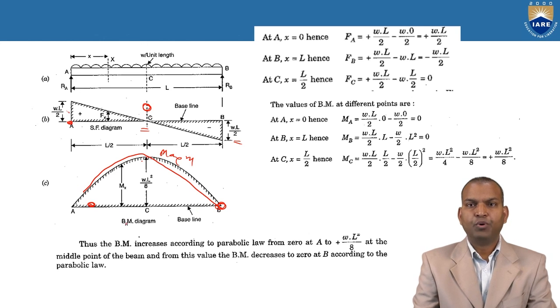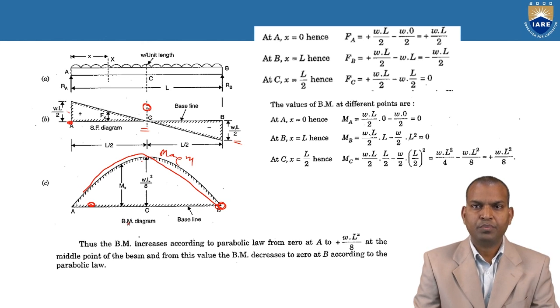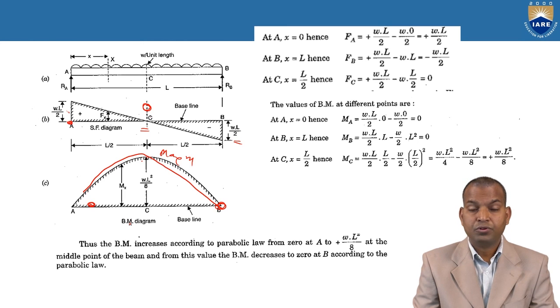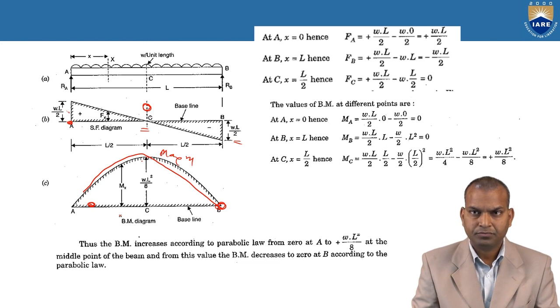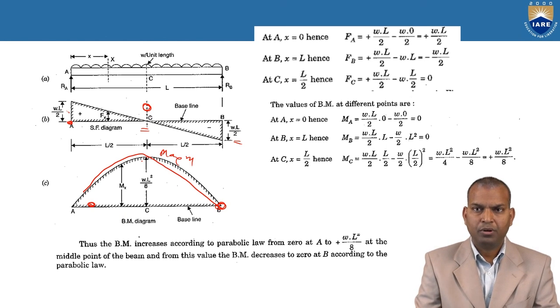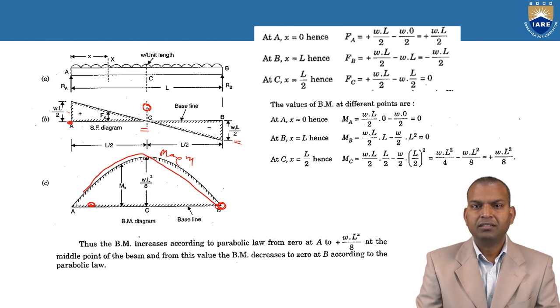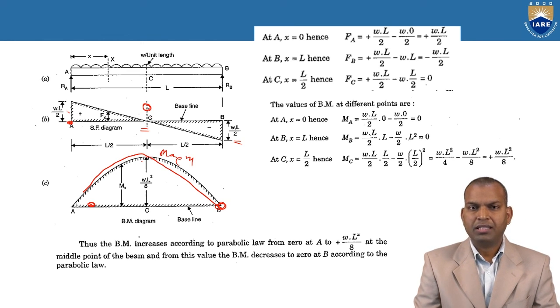At the endpoints of this simply supported beam, bending moments are 0, but shear force is acting at maximum values. So this is the conclusion we can understand. It is a very important problem in order to understand the variation in the effect of shear forces and bending moments when a beam is subjected to uniformly distributed load throughout the span.